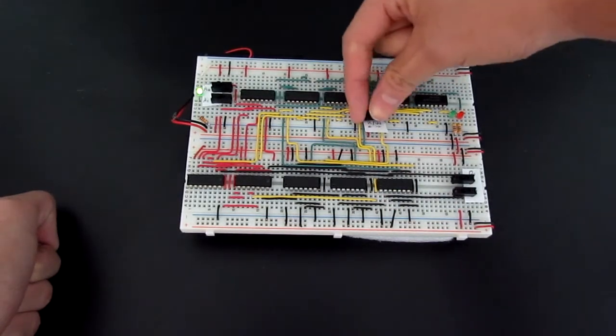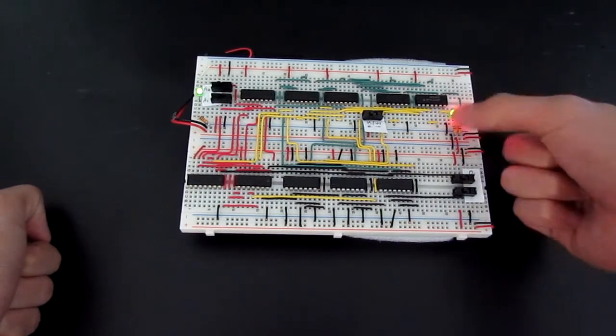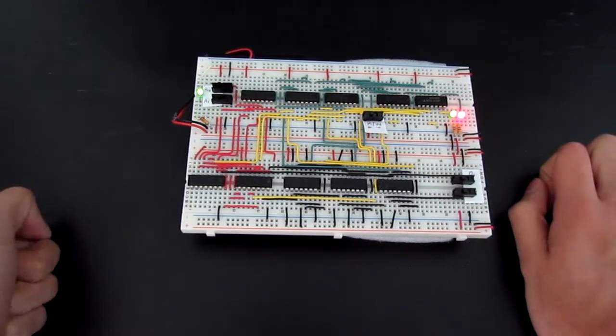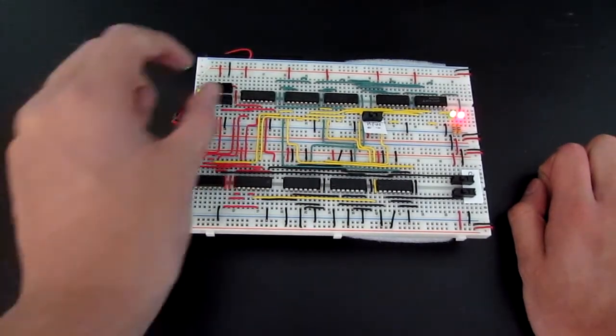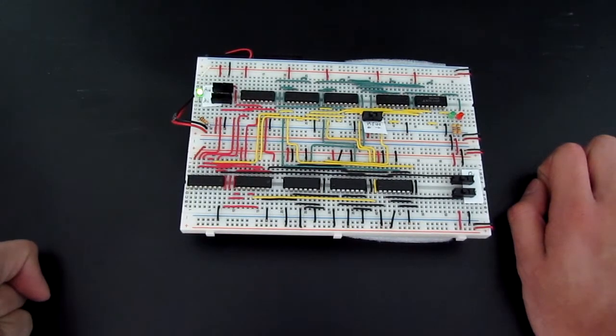Now we set it back to read mode. It now shows us what is in memory slot 3, which is 1, 1, being 3. And there we go, that's how we save a number. So, to save a number into different slots, we change the address leads and repeat the process. Remember, we can only save to 3 spots: 1, 2, and 3, being 0, 1, 1, 0, and 1, 1.